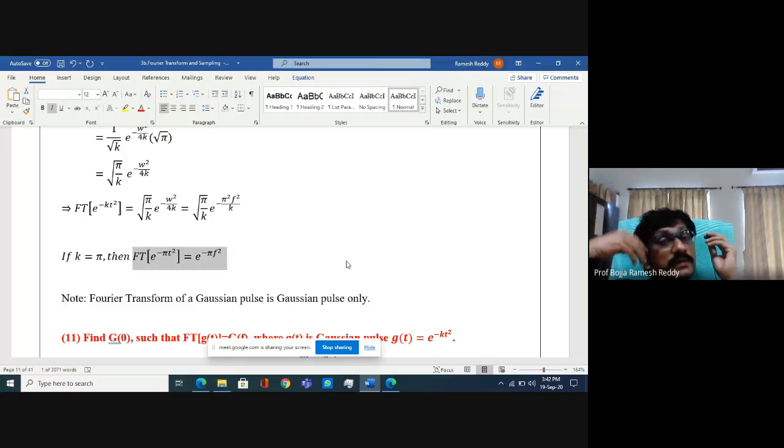In the remaining cases, Fourier transform of impulse is a DC signal, Fourier transform of rectangular is a sinc signal, and Fourier transform of rising, double or decaying exponential gives a spectrum with magnitude and phase, meaning the time domain is different and the frequency domain is different.